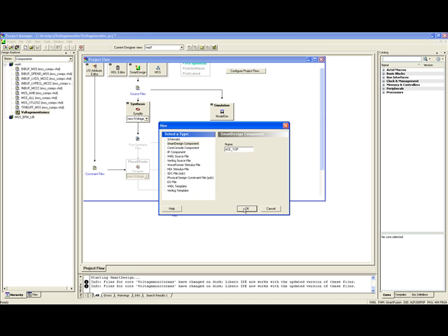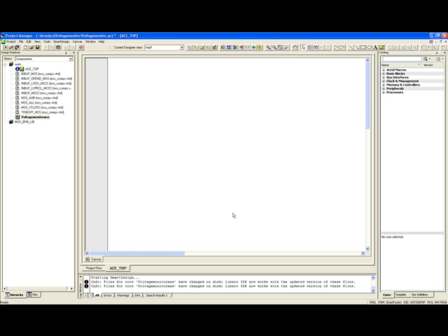Note that you can see the generated voltage monitor MSS component in the Design Explorer hierarchy window with an IP icon to the left of it, indicating that it is now an HDL component that is ready to be instantiated into the top-level design. Drag and drop the voltage monitor MSS IP component from the Design Explorer onto the SmartDesign canvas.